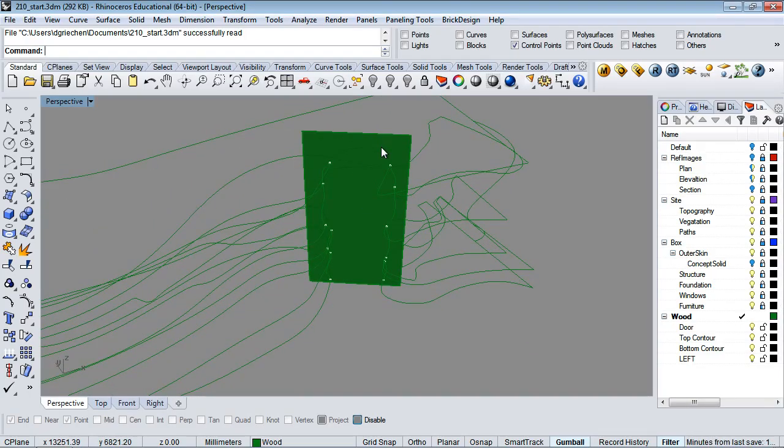So everything that is built, generally, it's a little bit easier if we can always go around and define what is X, Y, and Z relative to this complex 3D geometry. So what we can do is create a plane, and we can tell Rhino we want this to be the construction plane. This is the surface. This is the X, Y coordinates that we want to start to create geometry on. Okay? So this is really handy when we're doing cross-sectional curves in complex geometry.